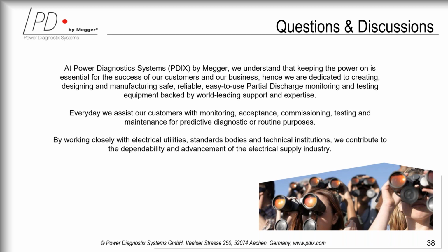Also, as Mihai had mentioned in his presentation, there are several different sensors, and you could use acoustic sensors also to help locate defects within your high voltage asset. So just by analyzing the pulse shape and where you're testing from, this will help you to identify the type of defect and where that may be.